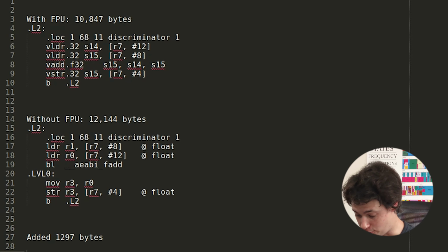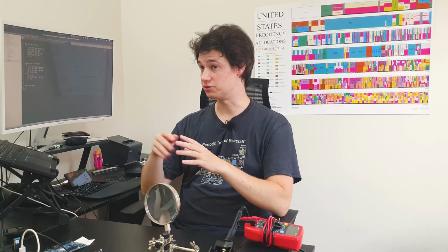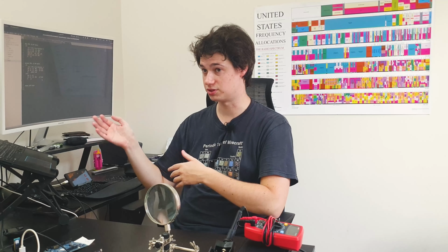That's for you to decide in your own software, and finding ways of going around it, or implementing fixed point calculation, which is an entire technique that we might do a video about in the future. But that's it. That is the reason why floating point calculations are to be avoided regarding memory. There are also reasons to avoid them regarding precision and errors of calculation in some cases. That's why in embedded systems, fixed point calculation is often preferred. Now that we got hardware FPUs in some advanced microcontrollers, it might start to be a little bit more usable in some applications.